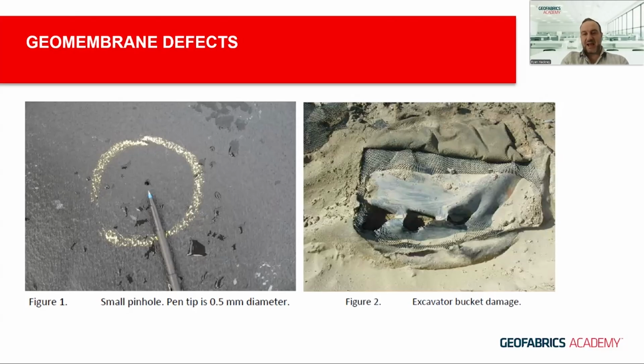So what's likely happened here is the geosynthetics have been placed, and then cover soils have been laid on top of the geosynthetic materials. They've been spread by machinery, and during that spreading process, the operator has somehow maybe gone too deep, or the spread layer has been quite thin, and that's caused teeth to damage the underlying geosynthetics. So including that barrier layer, which is the geomembrane, that's caused these significant holes from the teeth.